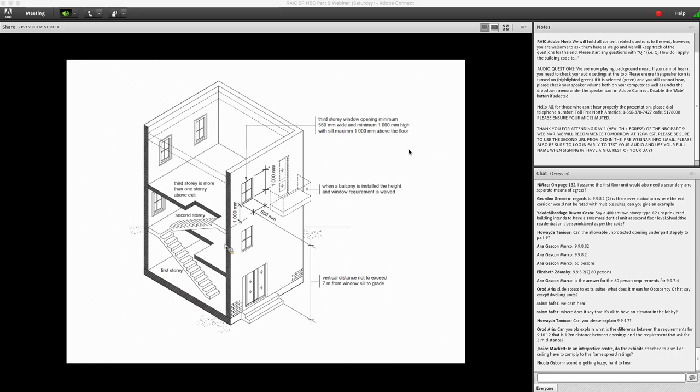So for a three-story dwelling unit, occupants on the third story will actually travel 2 stories to get to an exterior exit doorway, right? So the way around this is to provide either a balcony on the third story, or an openable window on the third story.